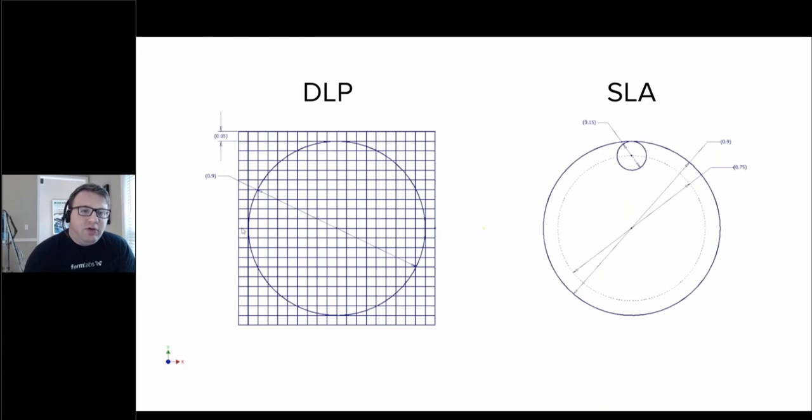And you can see while the software is deciding how it's going to draw this cross section, it's going to turn pixels on or off depending on if they're in the boundary or not. So in the 0.9 millimeter shaft, clearly these 2 pixels would be turned on, and then the software decides which other pixels are going to be on, probably by how much of the pixel is actually filled. So this one would probably be on, this one would probably be on, this one would probably be turned off. Regardless, it uses these series of pixels to draw this circle.